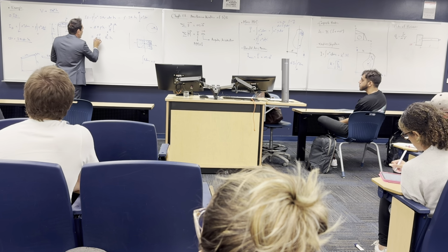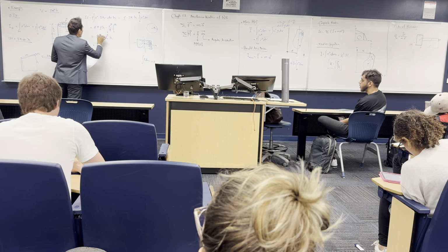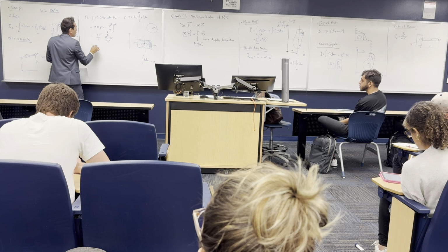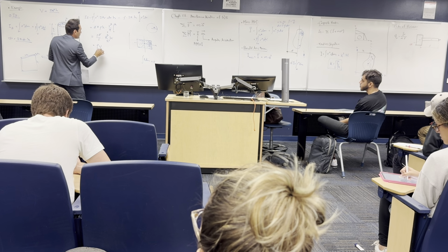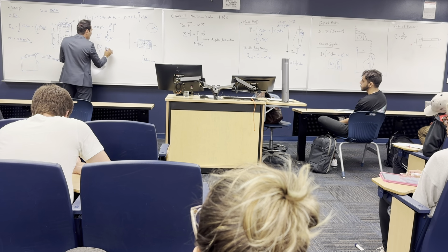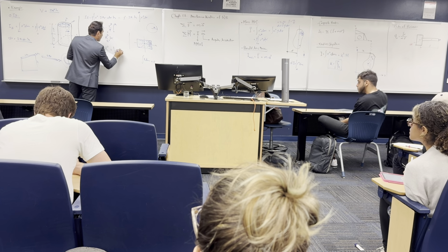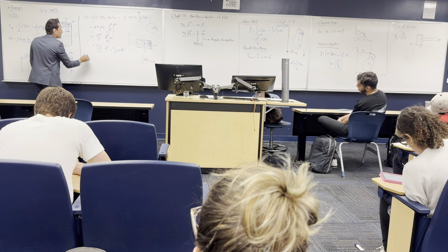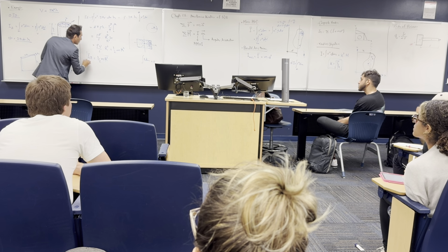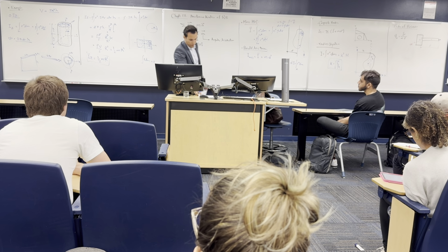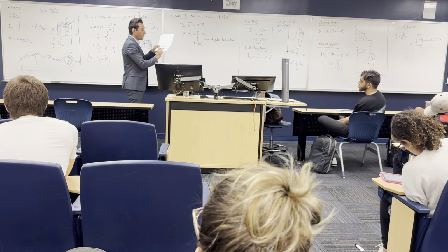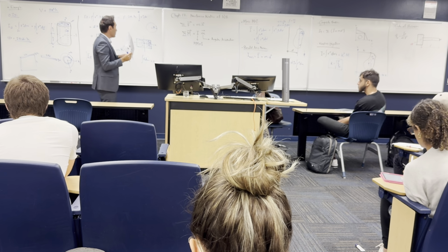Okay, so rho pi R squared h, and this is going to be R squared, so you'll have rho V over 2 multiplied by R squared, and rho V is the mass, so this is going to be half m multiplied by R squared. So the I of the cylinder about z is equal to half the mass multiplied by R squared. Let's check. Yeah, so that's what we have here. Izz is half m R squared.